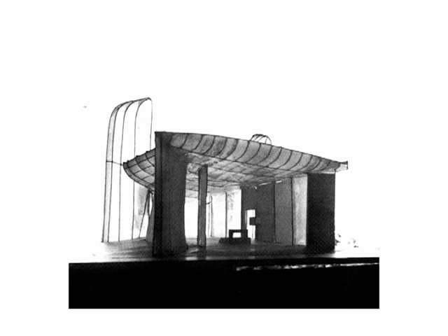There's a real precedent for this, though, right, in architecture. This is Corbusier's Chapel at Ronchamp. Believe it or not, the roof system is actually a waffle. It's not actually solid. It's actually hollow on the inside. It's a lot less concrete in a hollow thing, and it's not going to crush the parishioners, right? It's a waffle system. It's a series of waffle vaults. I mean, vaults are a common architectural entity too. So it's actually sections taken in the X and the Y.